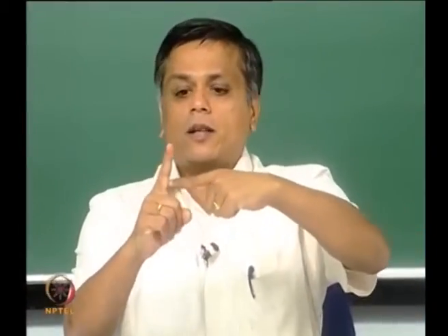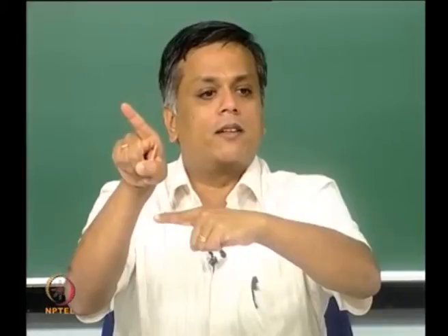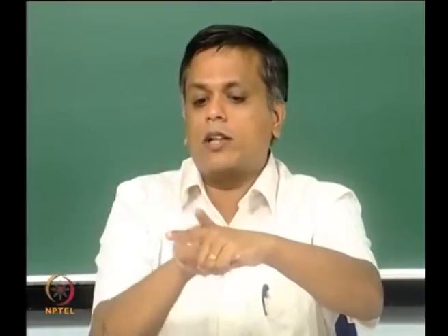It is like if I say I am moving at 3 meters per second this way, 3 meters per second this way, it is exactly like saying I am moving in this direction at 5 meters per second. Those two statements are exactly equivalent. So, when I say I am moving at 5 meters per second, I have no velocity in this direction at all. So, this sheet has a velocity root of u1 squared plus v1 squared in some arbitrary direction with respect to my current axis. But if I rotate the axis to be aligned with that flow direction, I can now consider a 2-dimensional instability in that direction and be done with it.